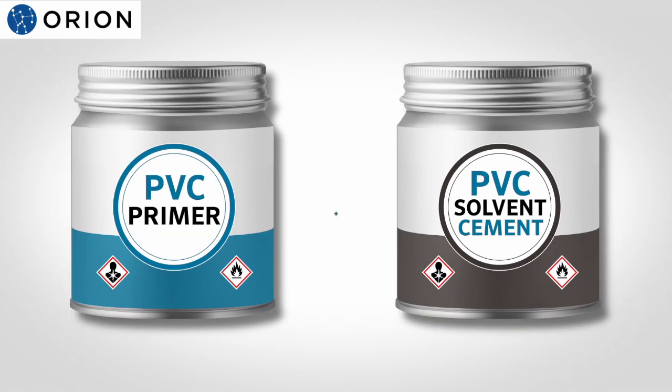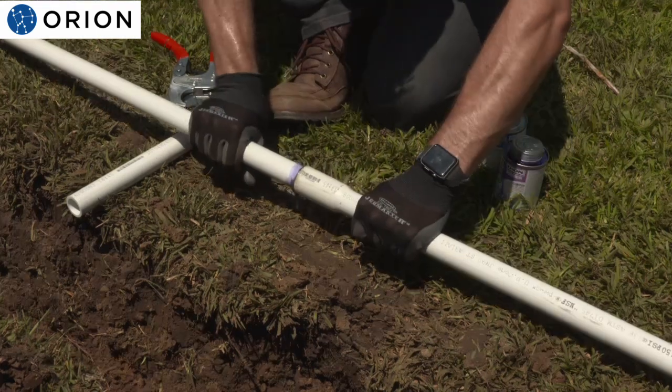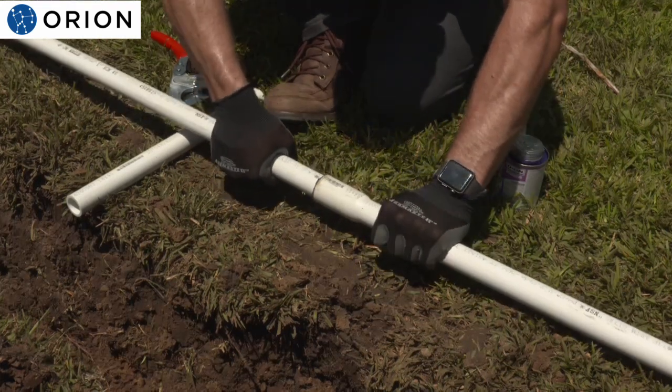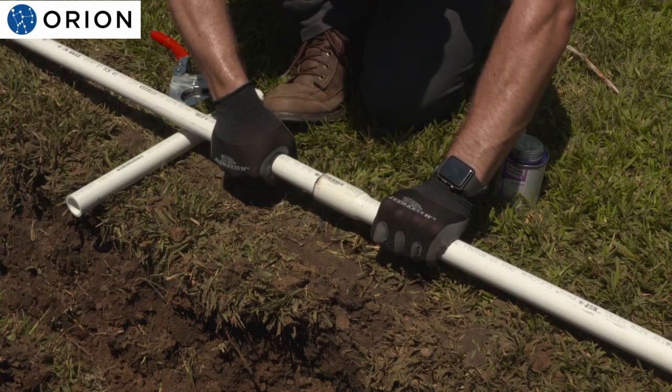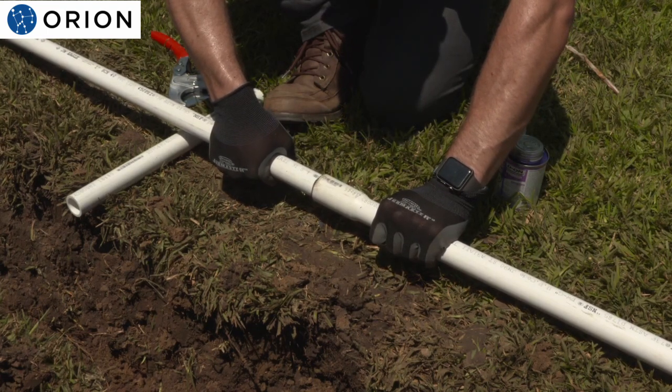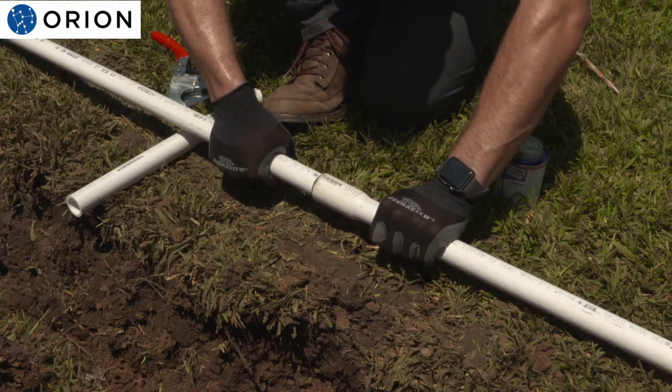PVC will most commonly be joined together with a combination of PVC primer and PVC solvent cement. The process is commonly referred to as gluing, but in fact it is a chemical reaction to fuse the two pieces of PVC together. Primer begins the chemical reaction that softens the PVC and provides an evenly prepared surface for the solvent cement to be applied for the chemical fusion of the two pieces.